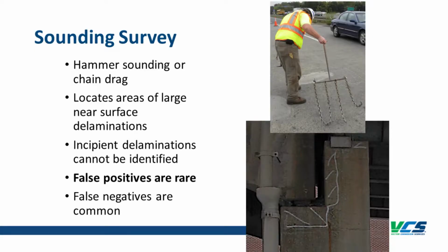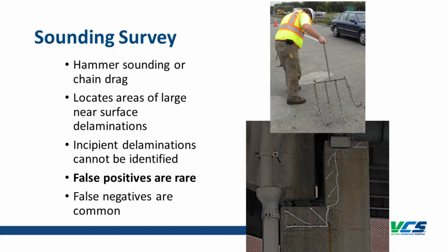better all the time. Sounding, another thing. A guy with a PhD, you wouldn't think would be really into sounding, but sounding is a really effective tool for one kind of weird reason. When we talk about non-destructive testing and data, we look at true negatives, true positives, false negatives, false positives. Sounding is kind of one of those weird ones where false positives are actually extremely rare. If you hear it debonded, you've got a delamination there.